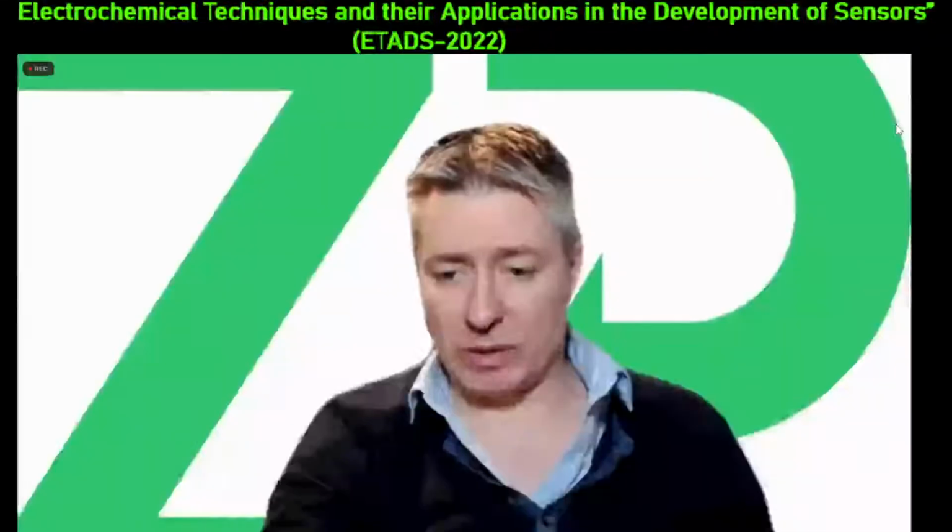This is, again, like Martin said, a potentiometric measurement. It's an ISE sensor in this case. So we have an electrode that's sensitive to the protons. And as the protons diffuse towards the electrode, then the open circuit potential will change. And that's how we make the measurement. So all right, well, thank you very much.